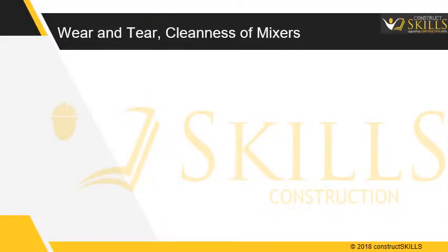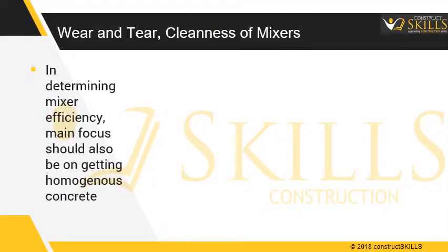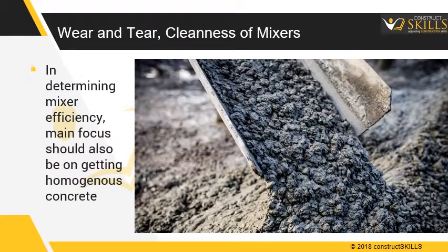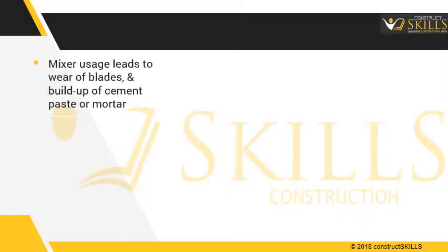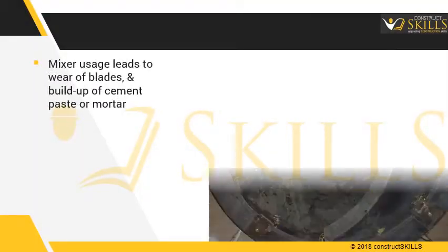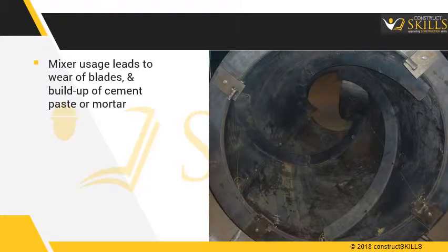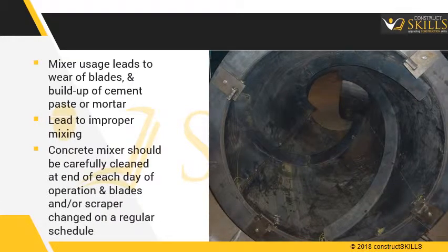Wear and tear, cleanness of mixers. In determining mixer efficiency, the main focus should also be on getting homogeneous concrete. Usage of the mixer leads to wear of the blades, and the buildup of cement paste or mortar. This will lead to improper mixing. The concrete mixer should be thoroughly cleaned at the end of each day of operation and the blades and/or scraper changed on a regular schedule.